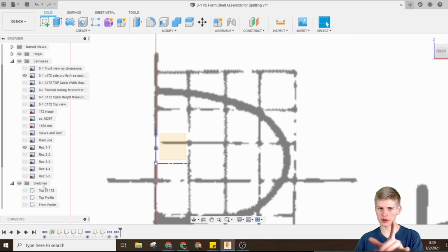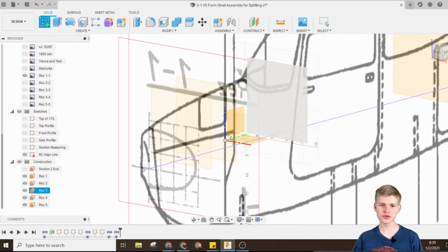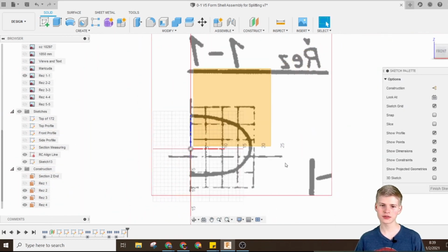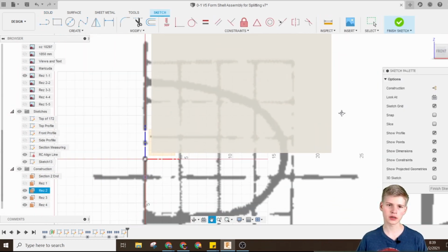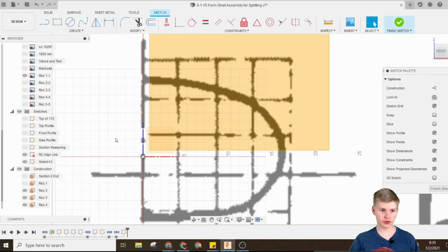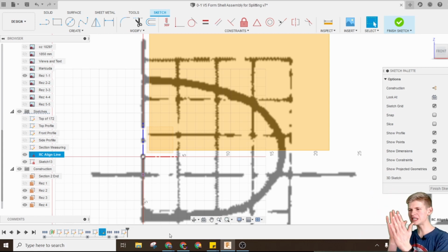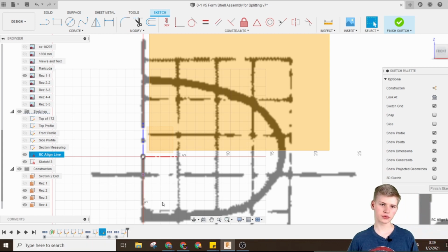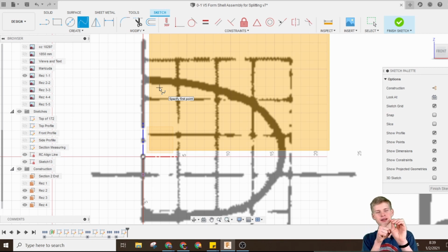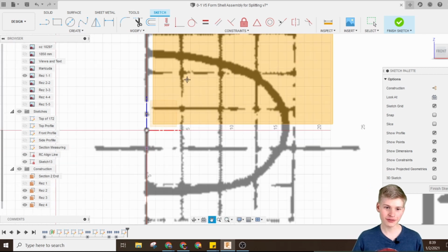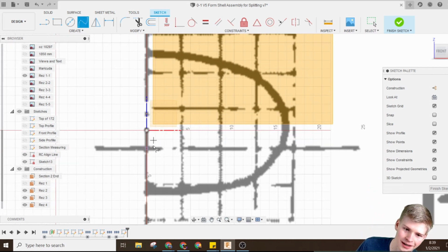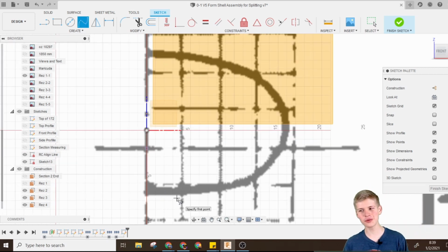Here's the sketchy part of this video. Make sure you sketch on the right plane, otherwise you have to recalibrate it and stuff, and it's a little bit annoying. But you can do it if you go to your sketch and say, redefine sketch plane. So you should be able to re-put it somewhere if you do it wrong. I'm going to see if I can make just a spline, a point, and an end point. I could even try just making a spline and an end point, but I don't want to live on the edge today. It's still early.